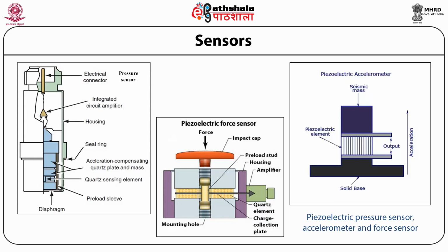The sensitivity of sensors is generally interfered with by other physical properties. For example, a pressure sensor shows a false signal when exposed to vibrations. Due to this, modifications in the sensors are made to deliver accurate readings. In sophisticated pressure sensors, acceleration compensation elements are used in addition to the pressure sensing elements. By carefully matching those elements, the acceleration signal from the compensation element is subtracted from the combined signal of pressure and acceleration to derive the true pressure information. Now the figure below shows the piezoelectric based force sensor.